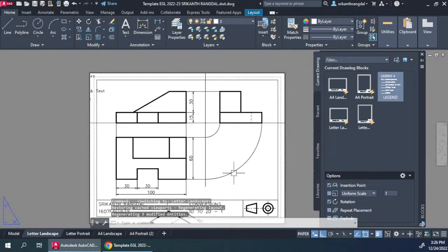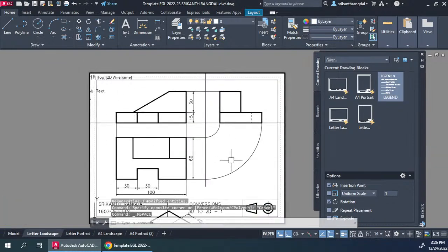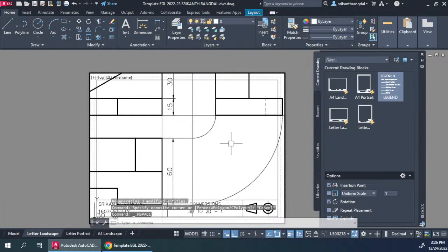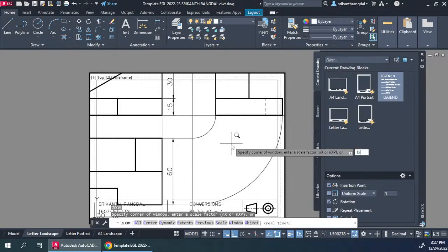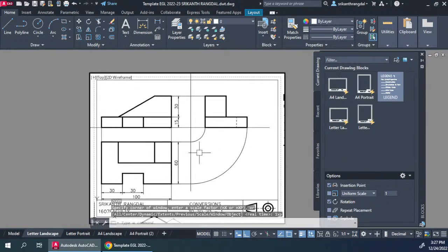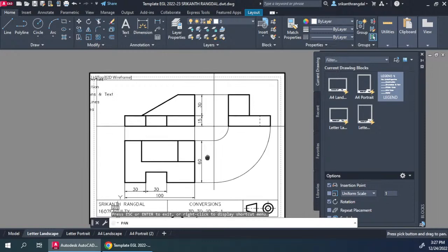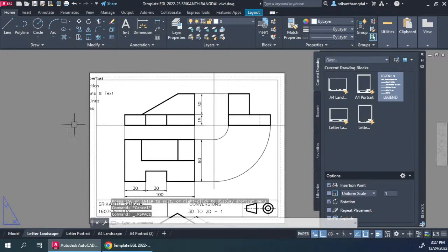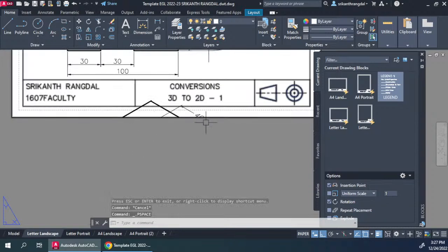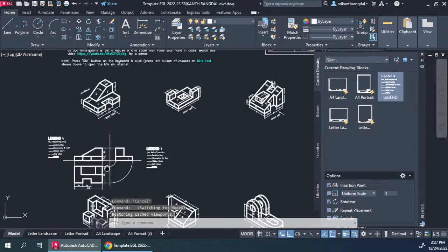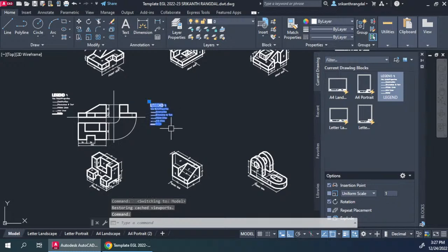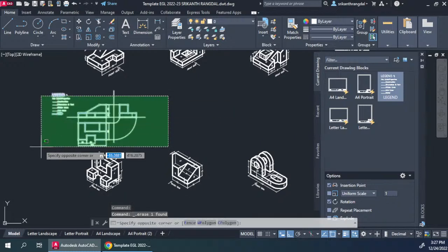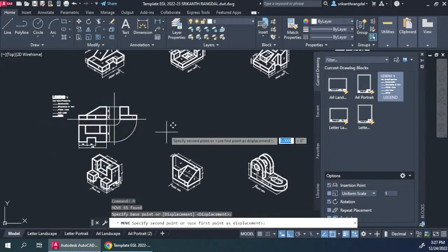Right, so now we have fixed it over here. Okay, so double click here. If the size is different, Z enter, 1xp enter, and then P enter for adjusting it over here. Once it is adjusted, double click outside, and if something else is coming here inside midway, you can just move it over here.